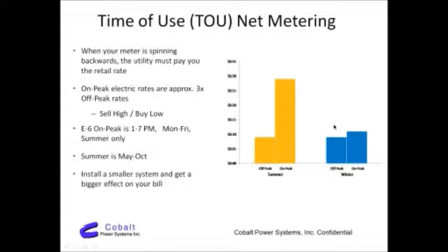In the wintertime, the rates are low. There is no peak charges. It's only off-peak and partial peak. And that, again, is advantageous because in the wintertime we get weather. And if you had a peak time in the winter and you had a rainstorm come in or cloudy days or something like that, you'd be paying those peak charges. So in the wintertime, your PV system doesn't produce quite as much, and we do get weather, and so this is like a tailor-made rate schedule for people with solar.